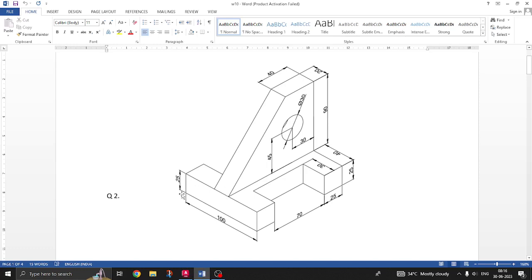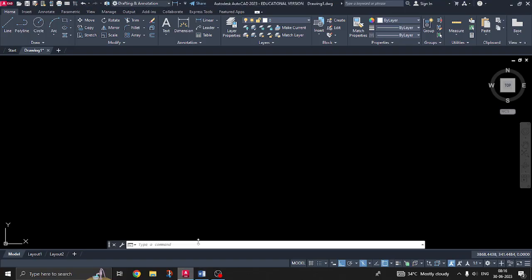I am drawing this diagram. Start from here. Okay, this line 125, 125 likewise. Okay, I am starting from this corner. Now taking line, and start, click anywhere on the screen. If you drag the mouse, it will show the straight line because of the ortho mode switched on. Okay, ensure that this direction 100, enter. Then upward direction, zoom, make center, pan it, upward 25.